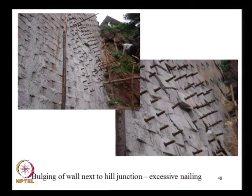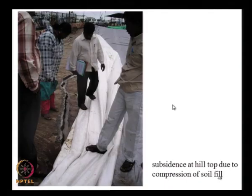So there were some problems, otherwise the entire system is stable, and you can see one modular block that has come out because of driving of 20 mm soil nails at a horizontal and vertical spacing of nearly 200 millimeters. That is too much nailing in these soil conditions.